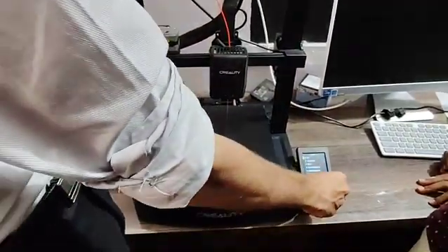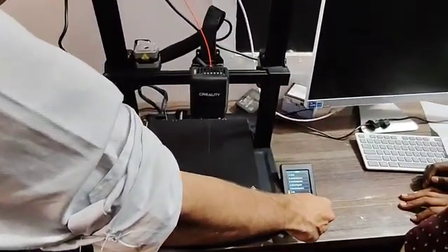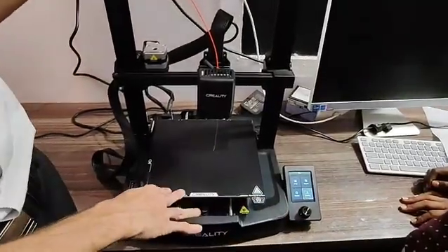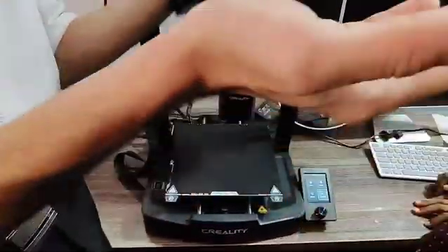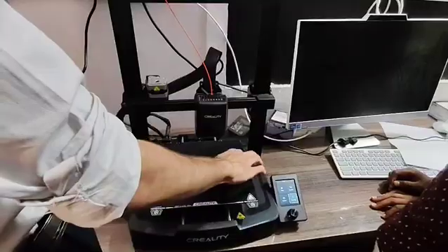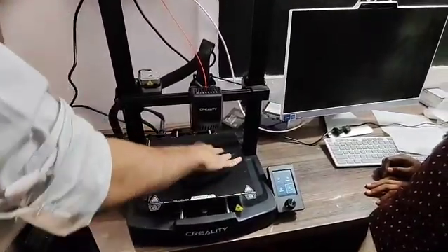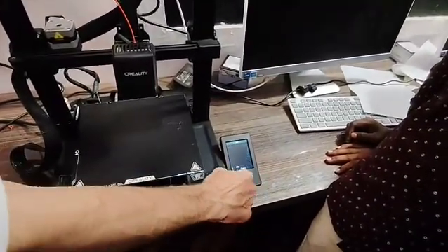You have controls. In controls you can set temperature, motion, storage, all extra configuration and factory set options. Leveling: the bed should be leveled. If the bed is a little tilted, when you turn on the calibration, it will take 16 points. It will get to know what the bed position is, and according to that it will print. Now if I want, we have created some model. If I want to print, I will just click